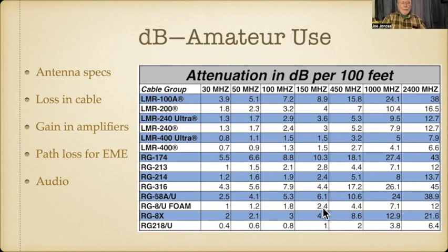Now, I want you to look at RG58. Notice that at 150 megahertz at 100 feet, it's 6.1 dB. That cuts your power.